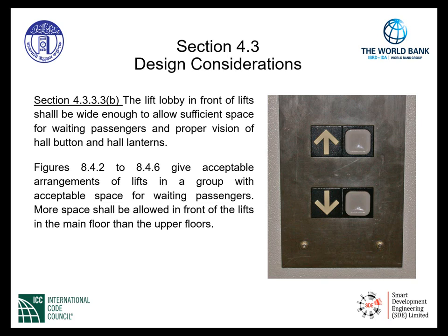Figures 8.4.2 to 8.4.6 give acceptable arrangements of lifts in a group with acceptable space for waiting passengers. More space shall be allowed in front of the lifts in the main floor than upper floors. It should be noted that it is preferable that the lift lobby is not used as a thoroughfare as well. But when absolutely needed, the lift lobby shall be wide enough to take into account the space for people who are moving.